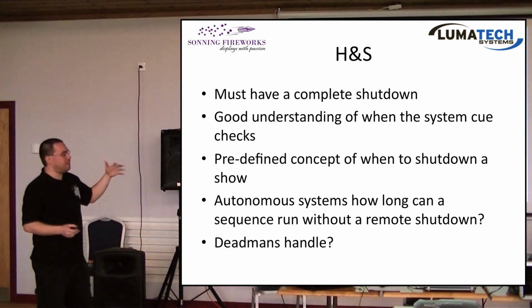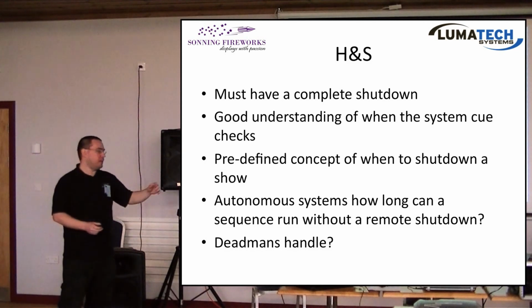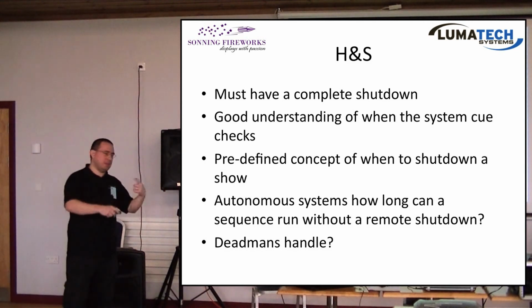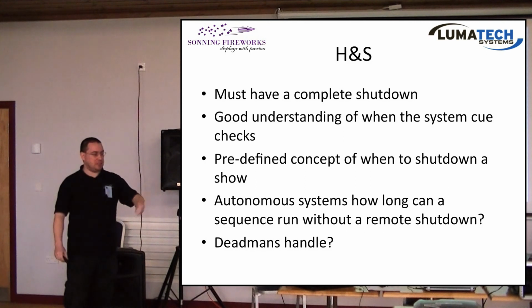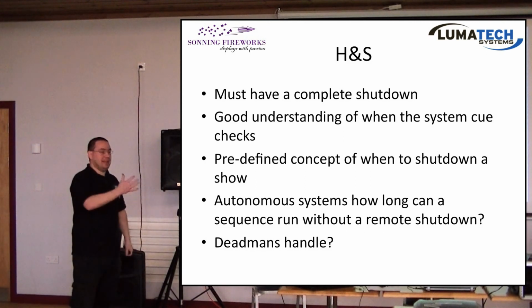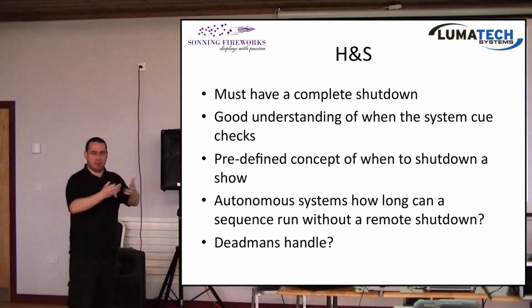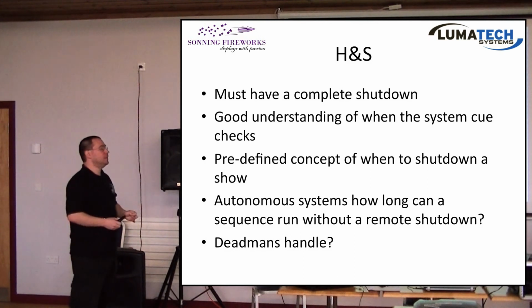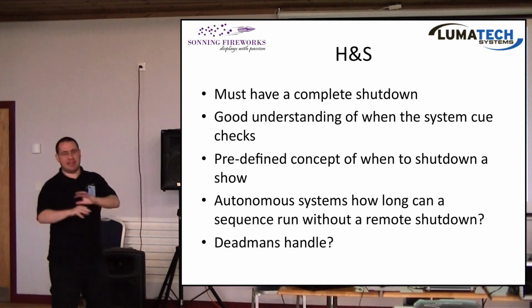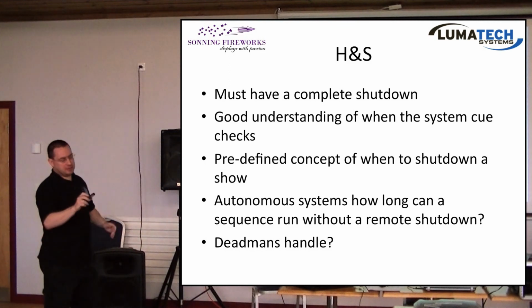And then the dead man's handle. A lot of the systems that send all the firing commands from the laptop, their dead man is to literally just disconnect the network. So you can hold your dead man switch, and when you let go, it disconnects the network and the boxes don't get any firing commands. If you want to carry on again, you just hold the lever down again, the network reconnects, and the modules start firing again. And like I say, ours is a bit more of a kill everything. You flick that switch and everything dies.